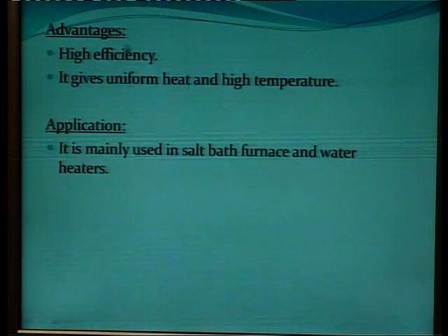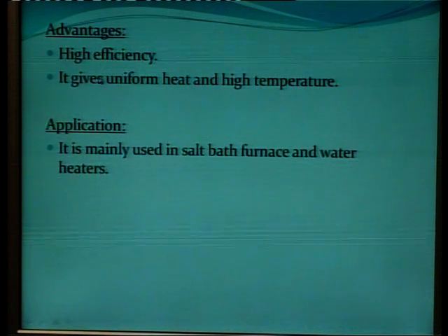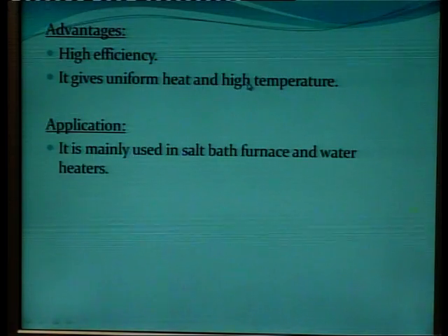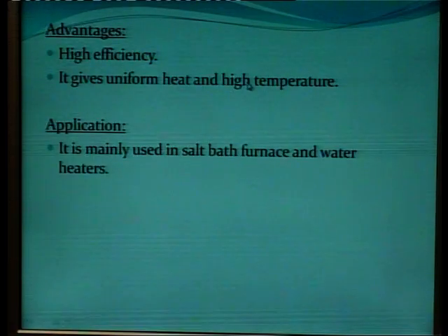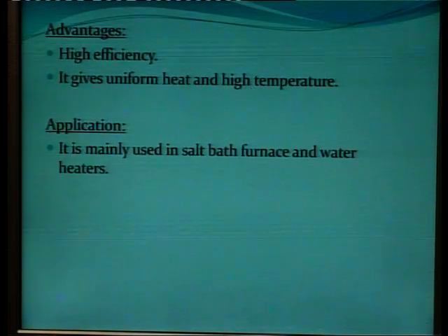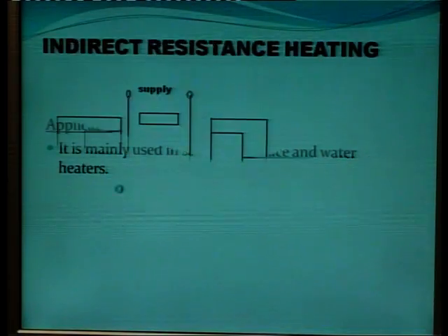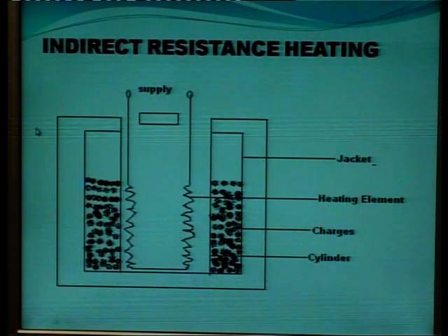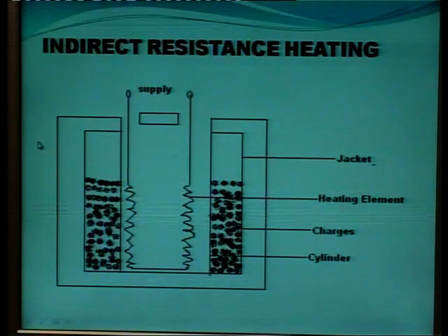Now the advantage is it has high efficiency, it gives uniform heat and high temperature. High temperature because the charge and the electrodes are in direct contact with each other. So that is why high temperature is obtained. Next is application. It is mainly used in salt bath furnace and water heaters. The next is indirect resistance heating.